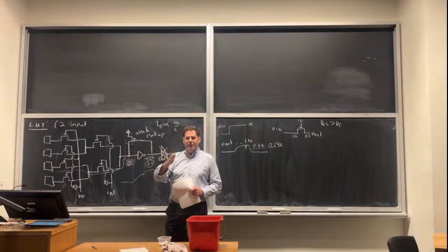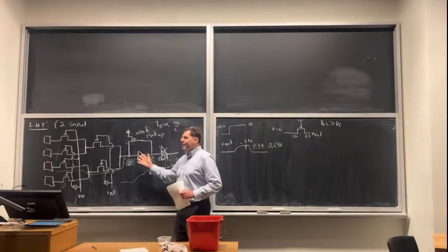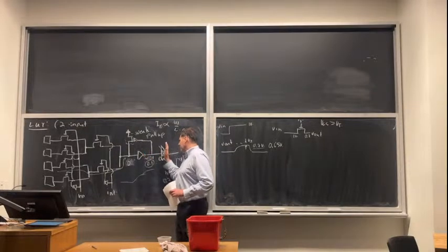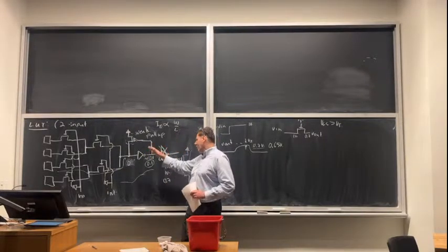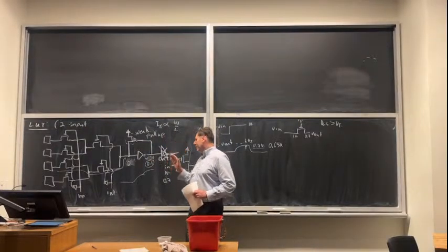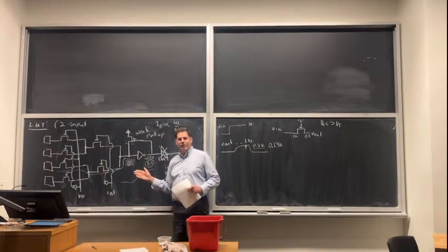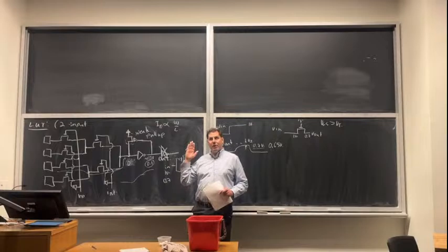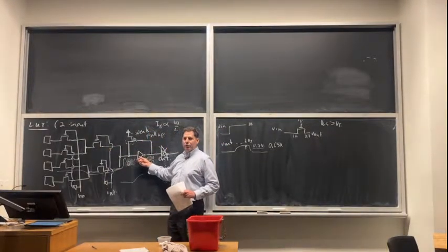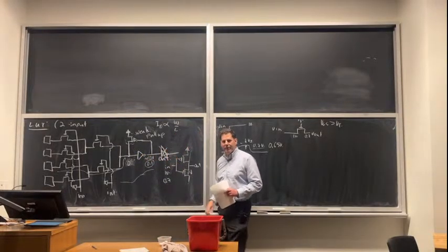You're basically trying to increase your drive strength. And if you analyze what minimizes your delay, it's that you gradually increase the size. If you've got to drive a big load, you gradually increase the size of the inverters that are driving it, so that no one stage is loaded too much. If you make something with weak drive strength and you load it a lot, it's really slow. So you keep that load small and then gradually build up to drive a big load. Does that make sense?